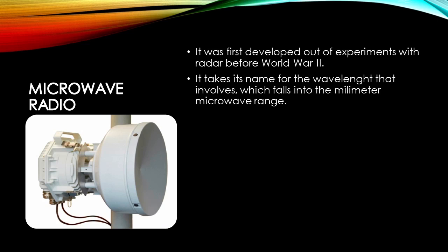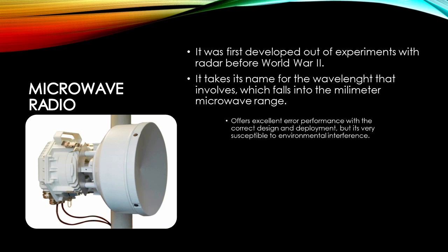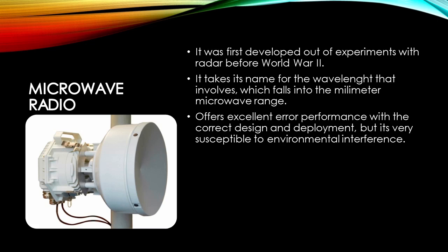Such high-frequency signals are very susceptible to attenuation. They must be amplified if they are analog or repeated if they are digital. For the configuration of these systems, we use antennas centered with reflective dishes which are attached to structures such as towers or buildings and generally take the shape of a parabola or a horn. While antennas offer quite a small range, large horns collect more incoming signals and therefore have a greater gain, or increase in signal power.